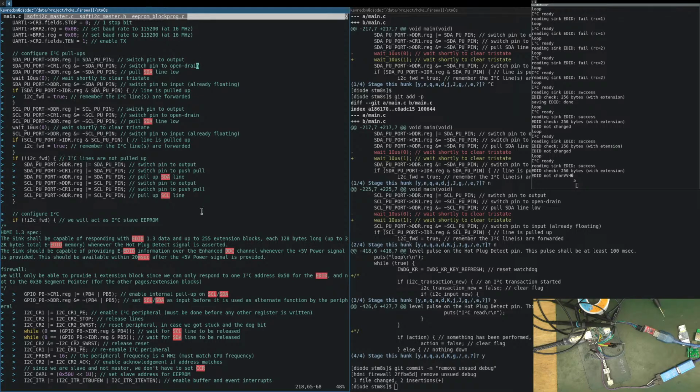So here I open-drain pull low. And actually I already pull low. That's weird. But I don't verify on the other pins. Check if pulled, if forwarded true. Why do I check? Check if it's pulled up. I shouldn't check on this pull up. I should check on the SDA lines, not on the SDA PU lines. My code is buggy right there. Yep, it's buggy right there.